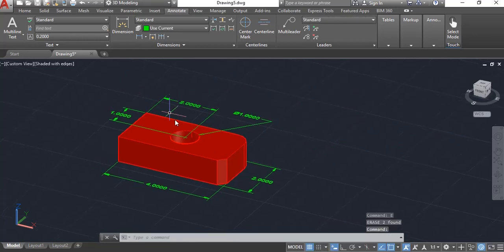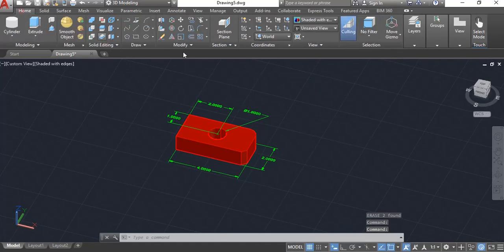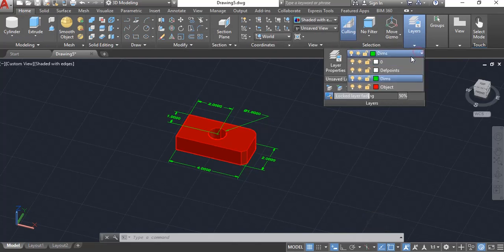All right, so we've talked layers here on setting them up. Let's say that we want to turn some off. So let me go back to my home ribbon, and let's say that I want to turn all my objects on the object layer off. I can hit the little light bulb and it's going to turn that off. I can hit the freeze thaw, it will turn that off too. There are certain items that, if they're on a certain layer and you hit the off, might not necessarily hide. So certain types of blocks, for example, will do that. You have to hit freeze or thaw to make those disappear.